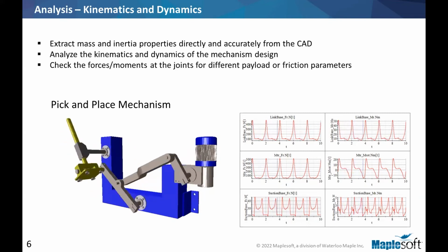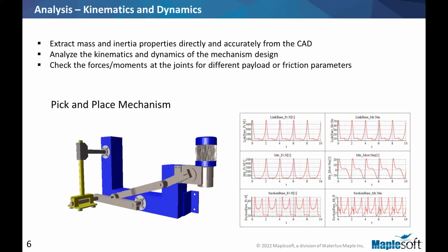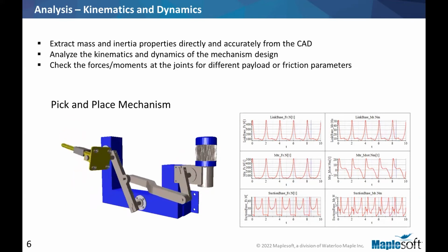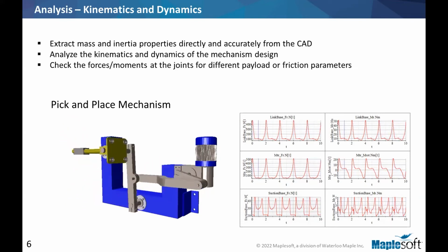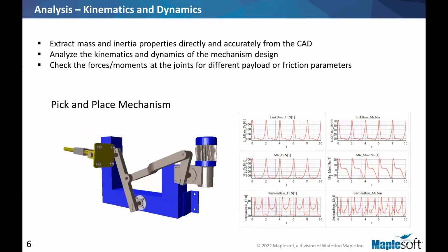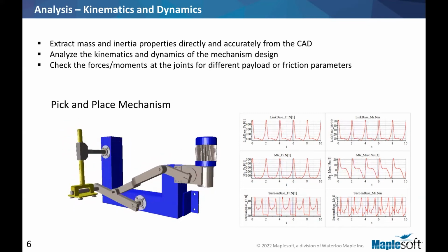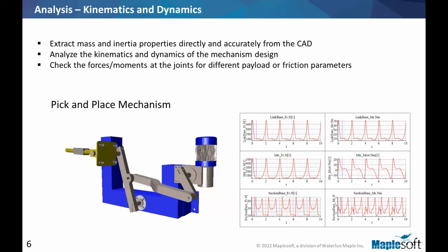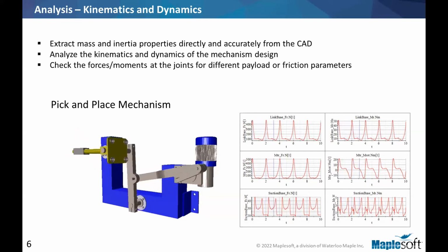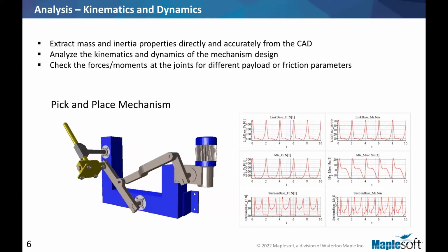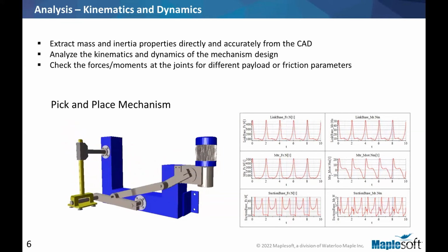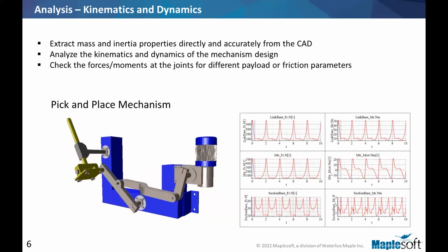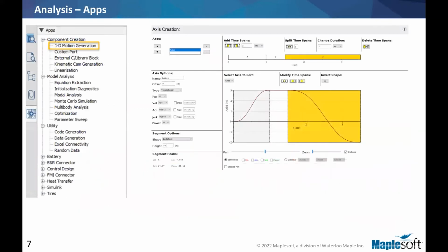Additionally, you can then go into your model and start doing things like adding some friction or damping in the bearings to represent maybe some kind of fatigue, maybe a lossy bearing. And then you can see how this can help you realize if your system is robust to changes or to failures. Lots of things that you can really analyze once you have your model. In this example, I was giving a constant speed to my motor, but of course, maybe you want to design some kind of more elaborate motion. We do have apps for that, as well as many other things.